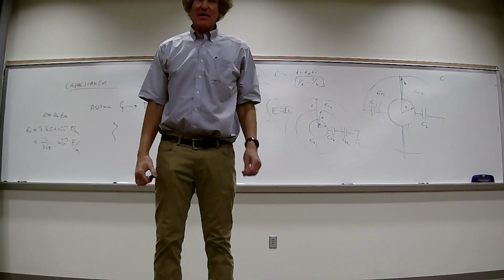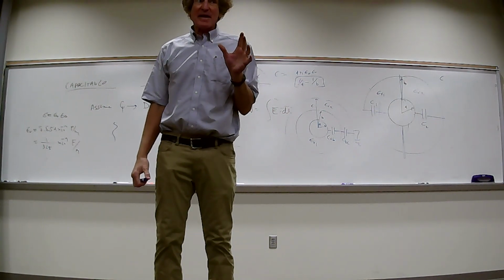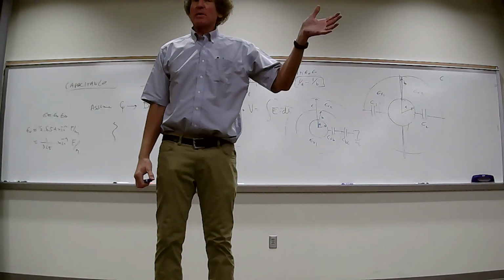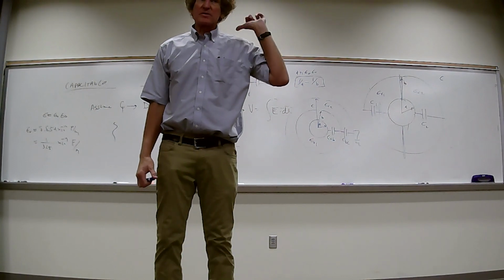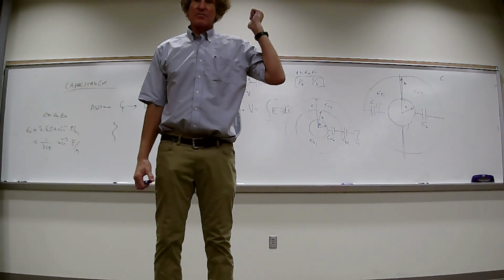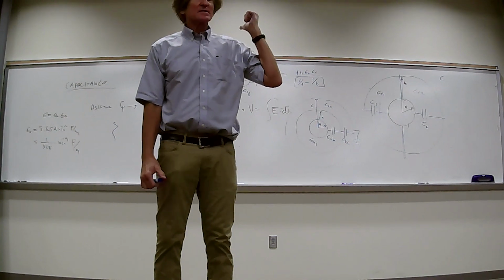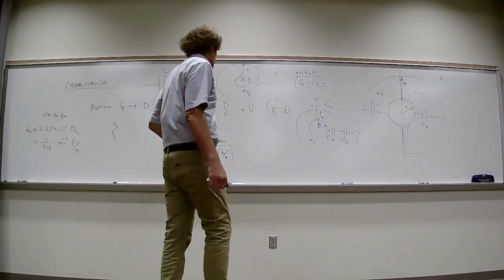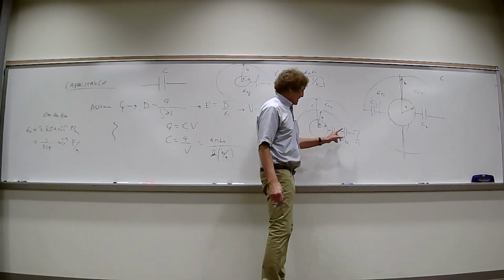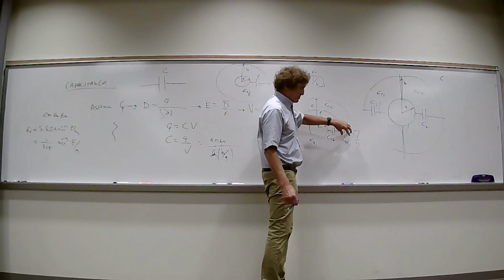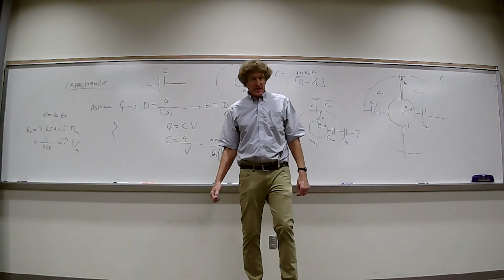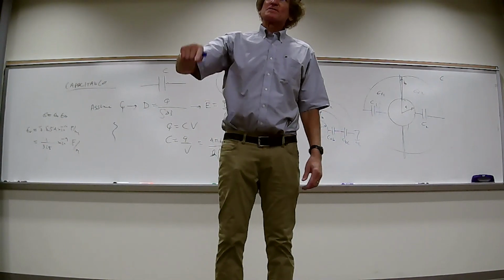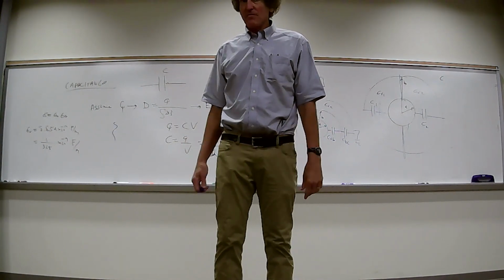That's right. Now, you see, we could go through the mathematics and assume a charge, get the D field, do all the nine yards on that, but it's a whole lot easier to see through the problem. Just realize that. Y'all follow me, class? I'm trying to give you some glimpses of the way I think about things. Go ahead. Do you not need a capacitance between A and C there? This is the capacitance between A and C. It's this one plus this one. That's all. I mean, you have to add them. Boy, I hate to do it. 1 over CAB plus 1 over CBC. Y'all follow me, class?